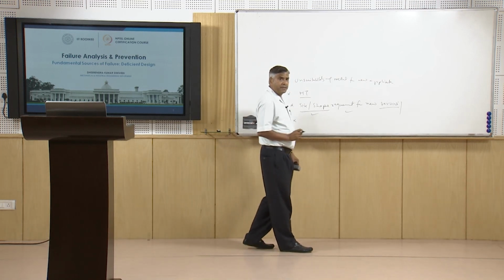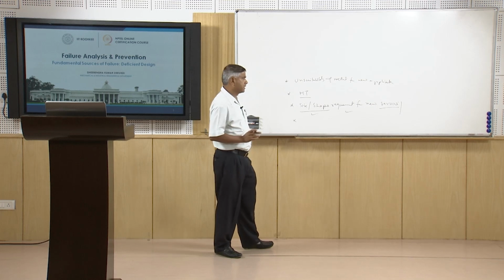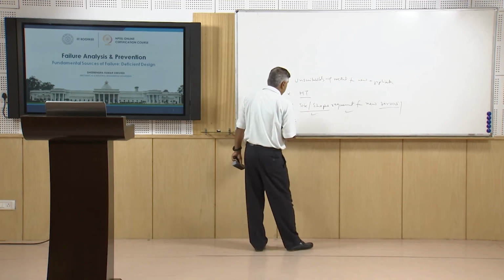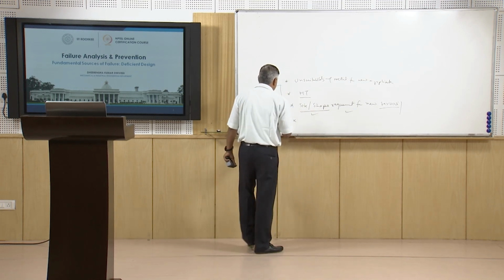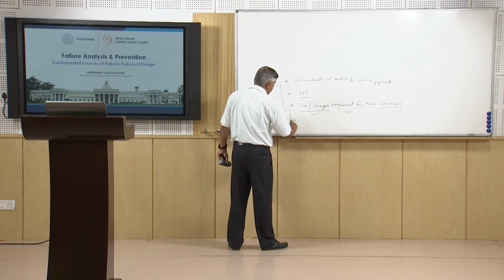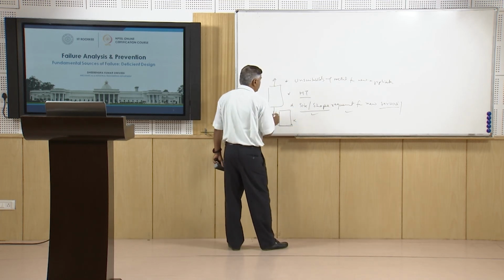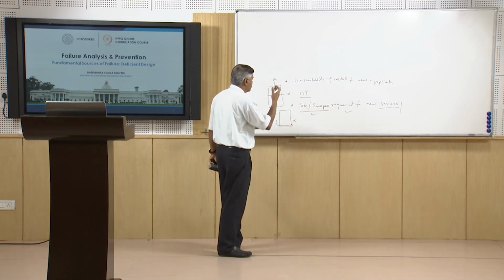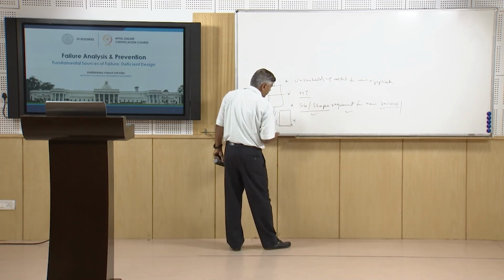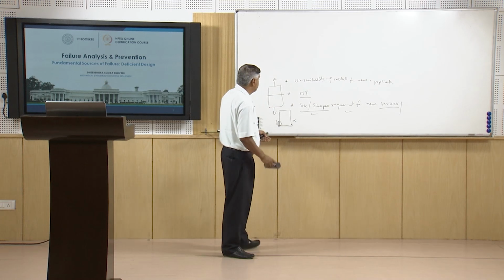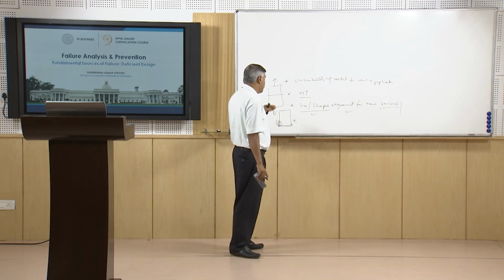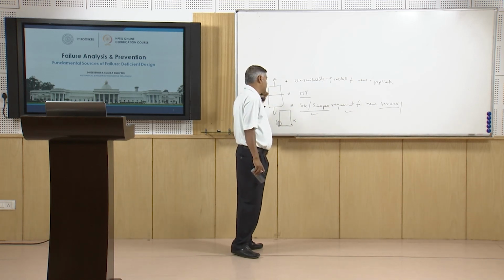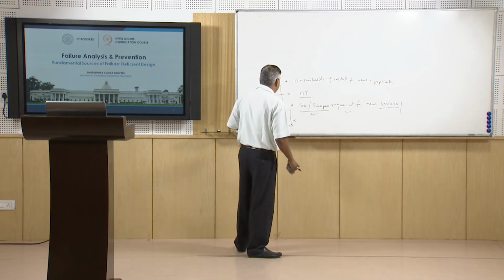Similarly, then we have the complex stress field becoming crucial for the newer stress concentration. Sometimes, like if the component was being subjected to the tensile stresses, and in the newer application it finds that it is being subjected to the torsional stresses. So, tensile stresses are uniformly distributed across the cross section, but in case of the torsional loading conditions, the maximum stresses are found at the surface. So, the discontinuities which are present at the surface may be more crucial for the torsional loading and for the bending conditions as compared to the case when the stress magnitude is uniform across the section.